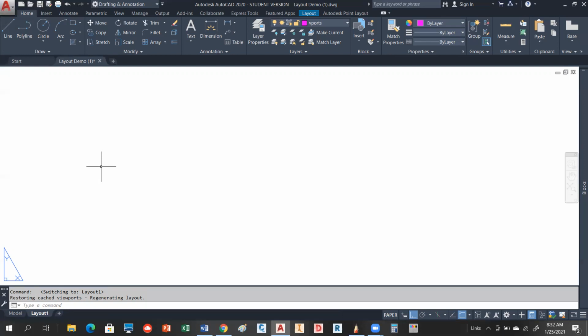And I could have 20 tabs down here, okay? So if I had an apartment building, let's say, and I had 20 floors, I could have a tab for each floor, even though it's just one model. So that's also kind of cool, because your drawing file is then just one drawing file, not multiple drawing files. And anything that happens on the model is reflected automatically in the viewports. All right, so enough talking. Let's go ahead. We're going to create some viewports.